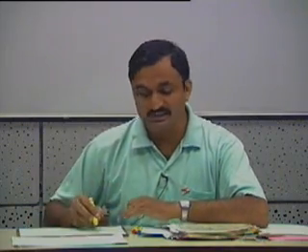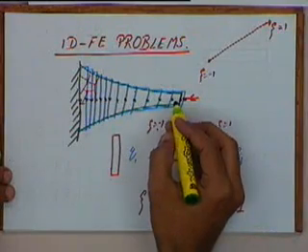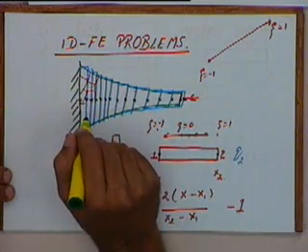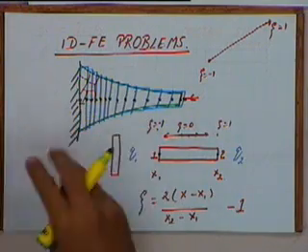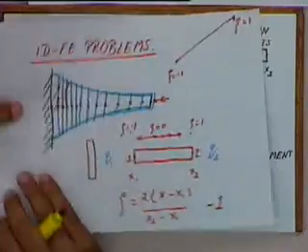After we've got the stresses at these points, do we interpolate? See, we are not getting the stresses at these points. We are getting a displacement at these points. Once I get the displacement at these points, I can get the strains within the element by using this relationship that I have just given.